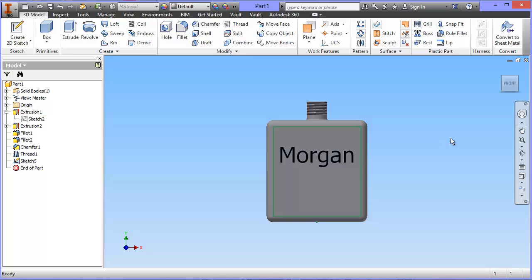And what I want to do now is emboss that thing. You'll see over here now it's created a sketch for me, but the sketch itself is just a sketch. It doesn't do anything until I tell it to do something. So if you think about it, it's actually invisible. It's not like getting a pen and drawing on something. These are kind of invisible lines. So on the real object, when we look at it later, unless I do something to it, I won't see those things. So I'm going to choose the emboss feature.